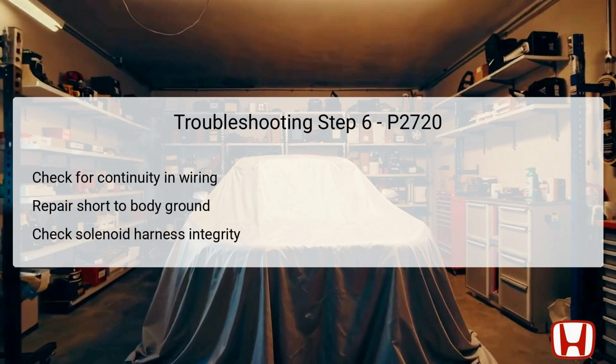In the final troubleshooting step, you will determine if there is a shorted wire in either solenoid wire harness A or B related to the LCC plus line. Conduct continuity testing between the connected points on the solenoid wire harnesses and the body ground of the valve body assembly. The vehicle must again be in off-lock mode, and the valve body assembly should be removed for access.